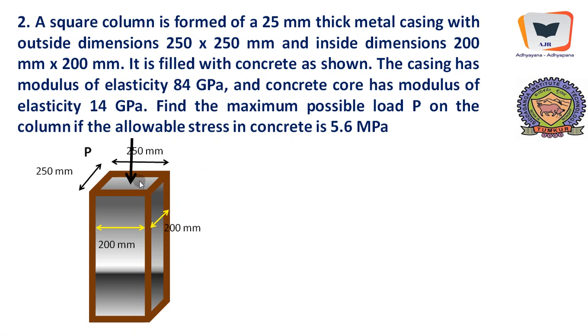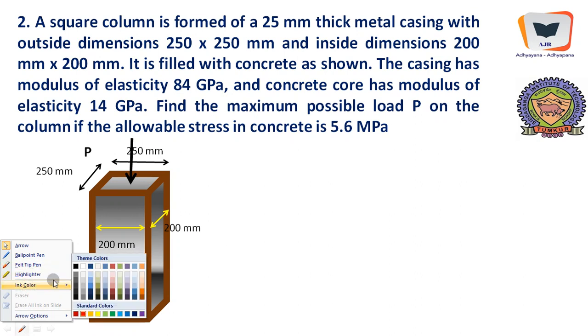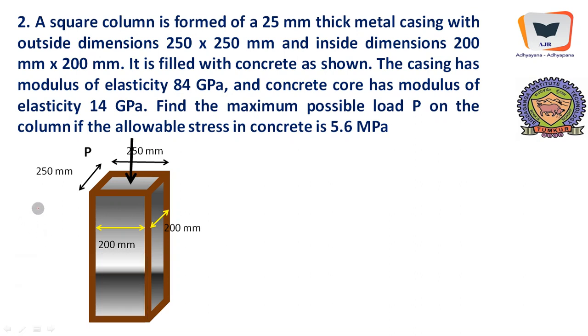However, the concrete is not strong in taking tension. Due to compression, the column will ooze out. When it squeezes out, assuming some kind of bulging, tension will develop over here. For example, if I approximately sketch the behavior of this concrete column, it has to bulge like this.